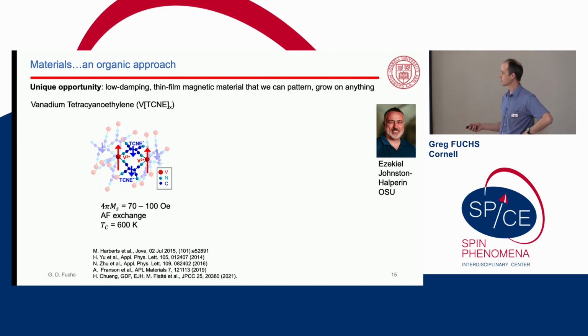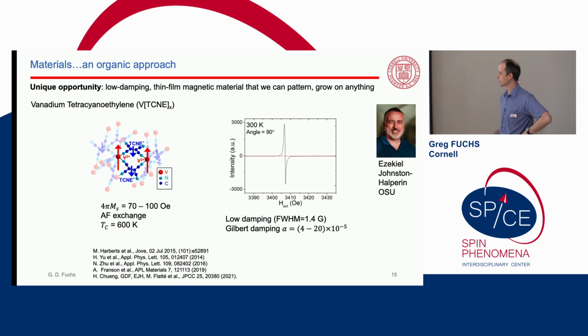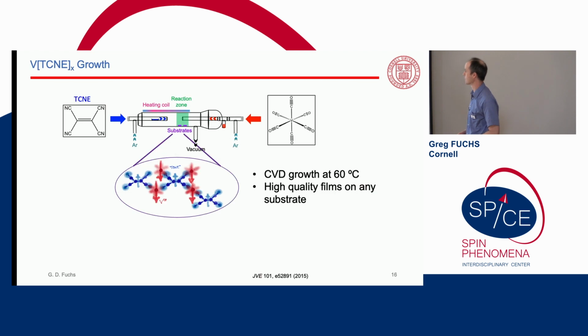But nonetheless, this ferrimagnetic material has exceptionally narrow FMR line widths, as narrow as YIG, and in fact, its room temperature Gilbert damping parameter is the only one able to tie YIG for the world record lowest Gilbert damping. So this seems like a very interesting platform to move forward on these cavity magnonic experiments.